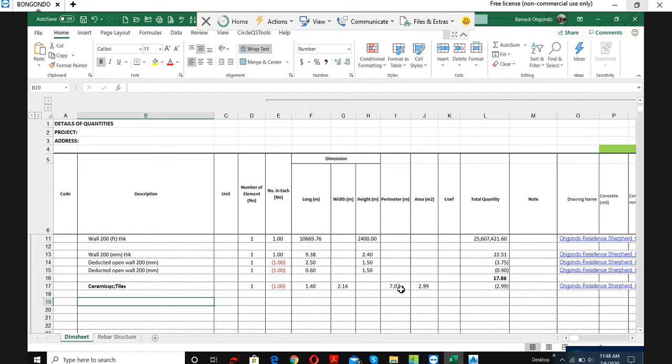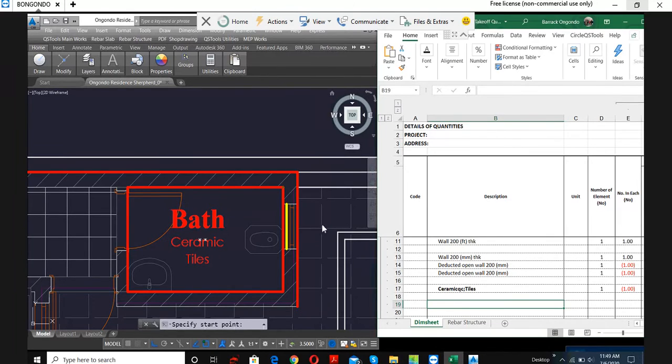But for formwork, it knows since there is an opening, it means on the edges of the opening to the slab, there will also be formwork. Then it also adds that formwork. It subtracts from the soffits, but it adds on the sides. You get?